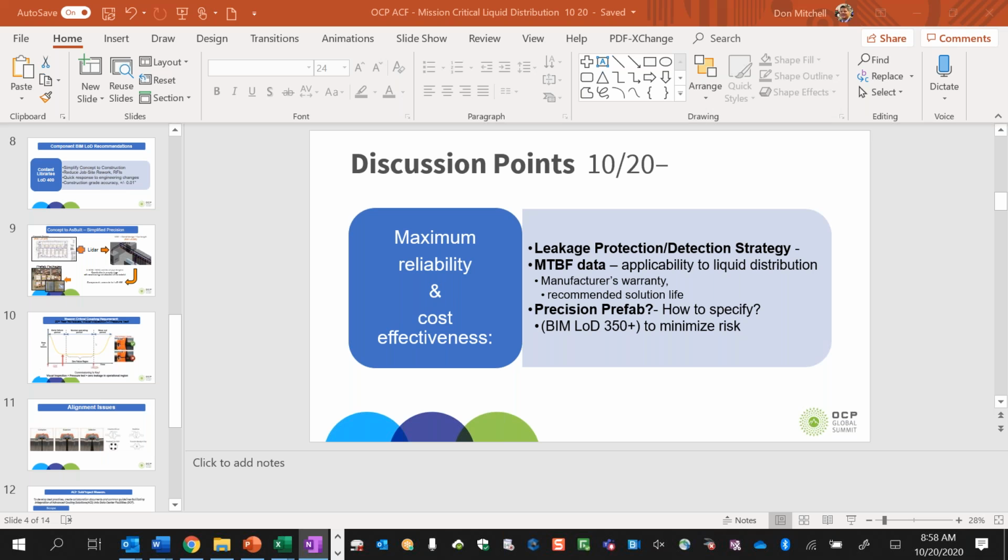And then the downstream of that would have been 2 inch flex connectors or flex pipe that was made in the field. So for example, on the flex pipe, we had the factory test the entire roll at 3x the design, and then we took that roll and put that into production, had ends soldered onto it and soldered onto them, and then those lines were tested also. So we didn't end up with a bad roll from the factory. Okay.